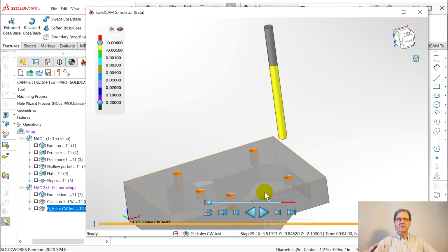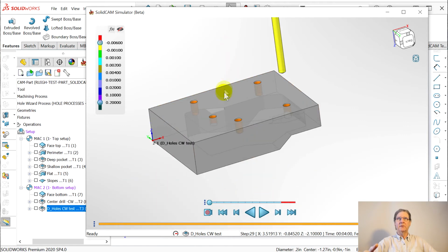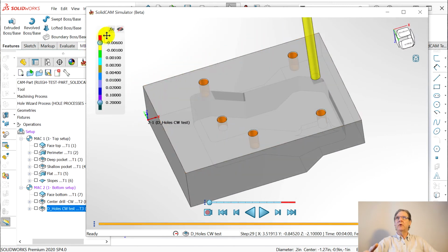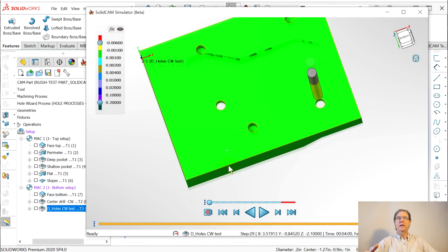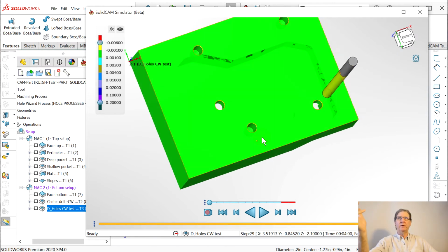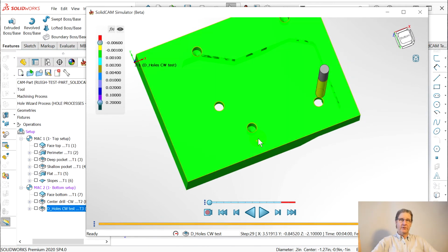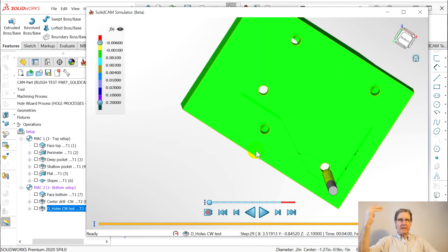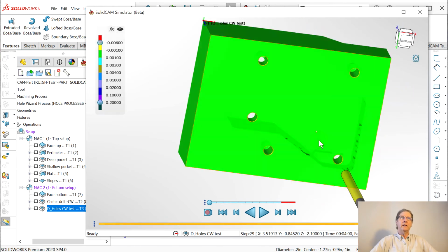This one, see, for my money, that's really worth a lot. So, okay, now it seems, doing the 0.44, and you'll see why I did that. You notice the bottom of the blind holes are green. This is within 1/1000th of an inch, 0.44. And I learned this doing all these other programs that do things wrong. Either they pick up the 0.38 from SolidWorks, and they don't use the SolidWorks Hole Wizard data. They just kind of measure something and decide, and then do the wrong thing.